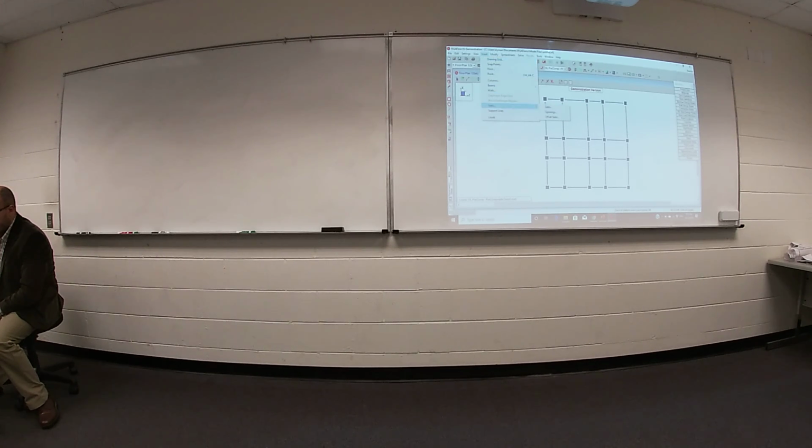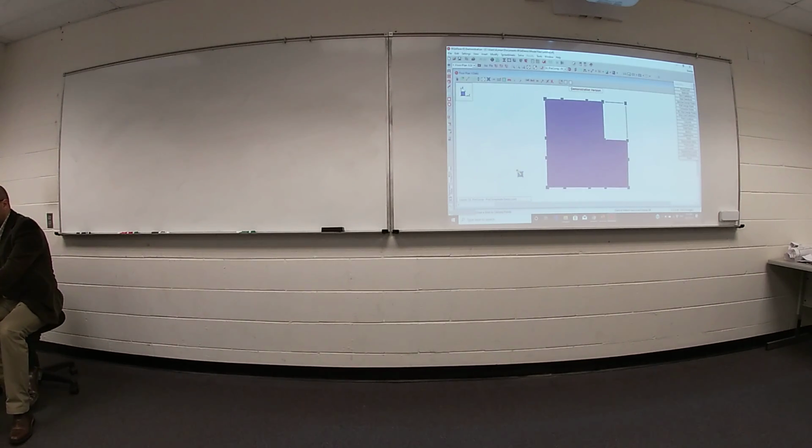What's wrong? Do you know? Your thickness 5 inch. Go back to draw slab and then apply from draw slab. Click at each corner. After you are done, please go back to the first corner you did and escape.